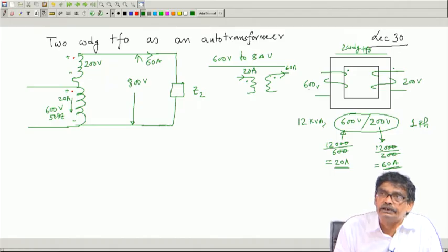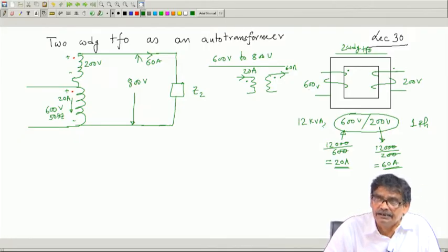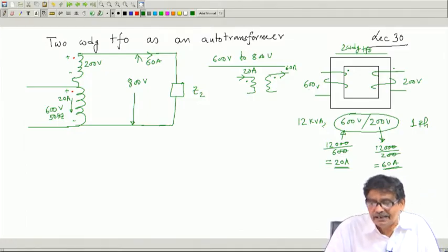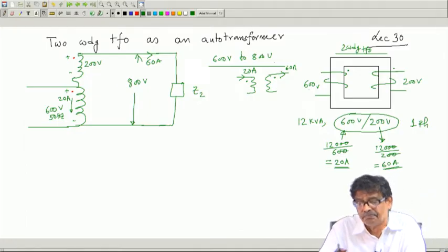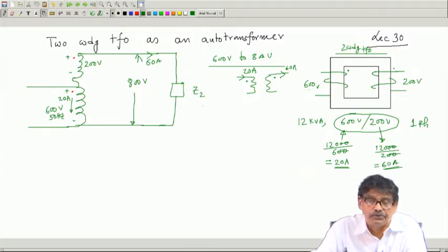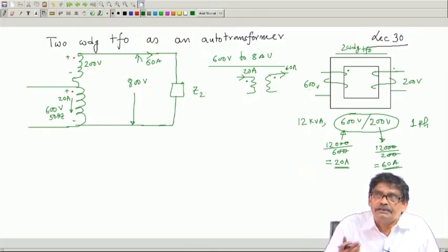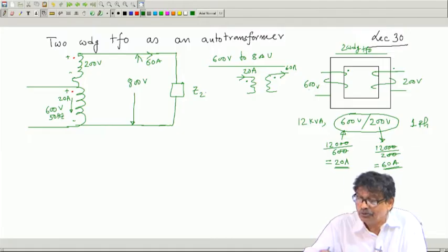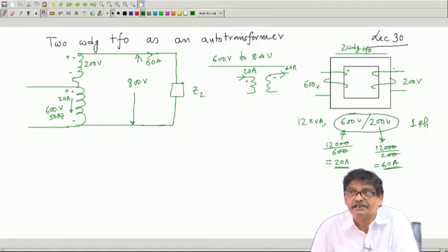Why it should draw 20 ampere? So that it can balance this MMF, so that the flux is created only by that magnetizing current, which is very little, because KVL is to be satisfied here, flux will remain same no matter what you are connecting across these two terminals. That is the good old explanation. Therefore, simply because you have connected in this fashion, to say those rules are not existing is not correct.